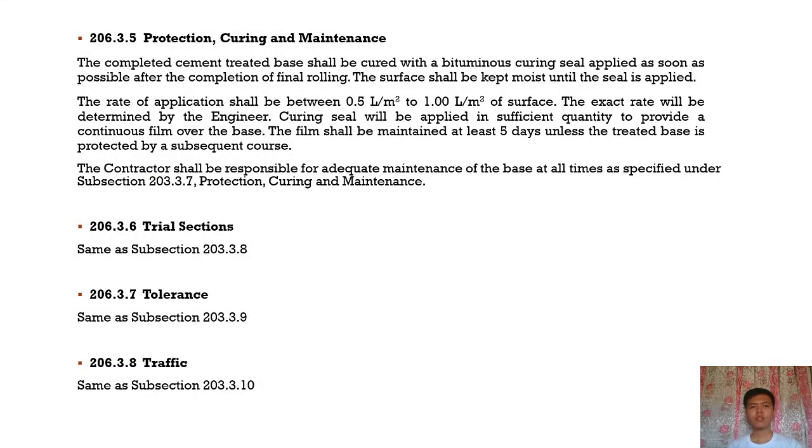Protection, curing, and maintenance. The completed cement-treated base shall be cured with a bituminous curing seal applied as soon as possible. After the completion of final rolling, the surface shall be kept moist until the seal is applied.